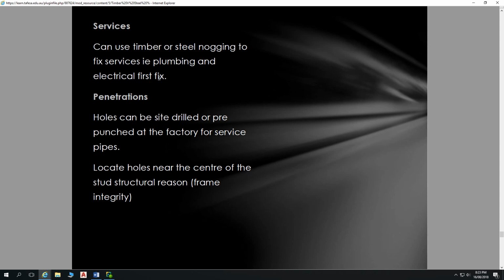One major issue with steel framing that was happening early on, and showed up later, was that with those light gauge steel frame studs being in a nice C shape, you had plumbers running pipes right up inside the internal face of the C, and then plasterboarders coming along fixing their plasterboards with plasterboard screws, screwing through the steel framing and straight into the plumbing, straight into the pipes.